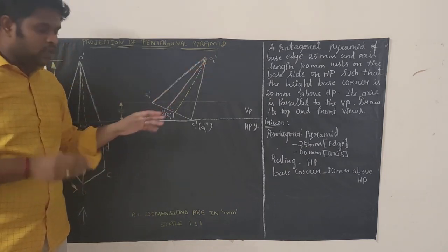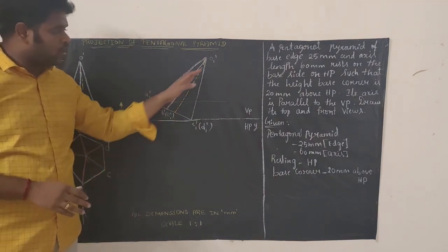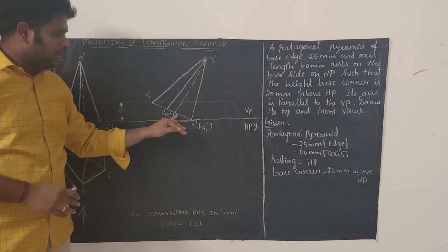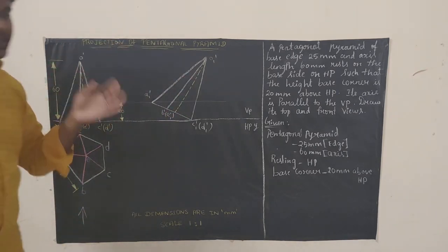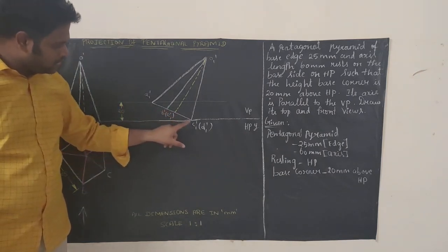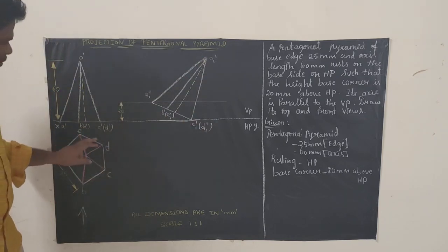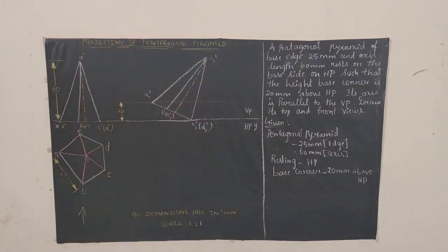This line will be drawn with an H pencil, and this is the axis line. You have to draw it as long dash, short dash, long dash, short dash. This is the axis line. Connect till the base. Right now we have completed this diagram, and the next step is to extend all the points, this point, this point, this point, and the O point vertically, as well as extend this point, this point, this point, this point horizontally, and then identify the intersection points and hidden lines.